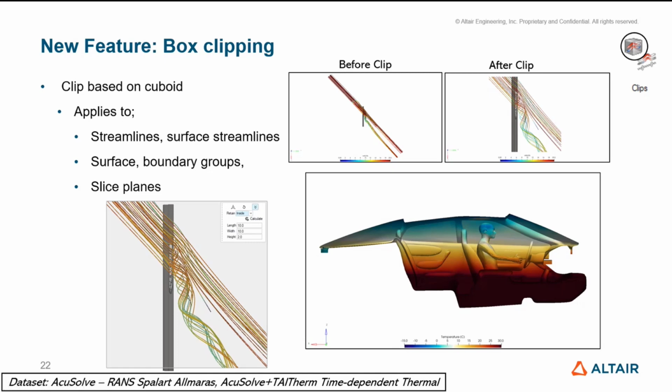And there's other ways to do this, but I thought this was an okay way to go about, say, clipping away half the cabin model. So that's what I did in this example on the bottom. We have the interior of a cabin with a human in it, and we can essentially just line up the edge points of that cube so that they hit the midpoint of the vehicle. And then we clip out all of the vehicle content that's sort of into the screen where the viewer is looking from.